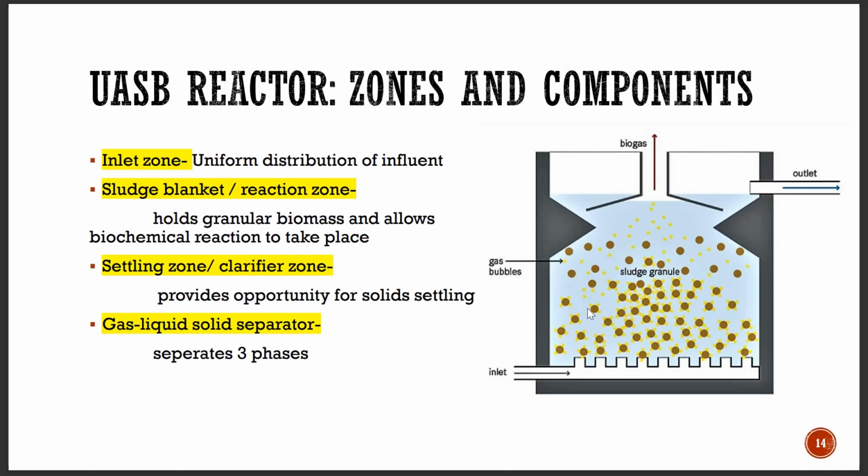So we do not require any kind of mechanical assistance or mechanical parts, it will happen on its own. When it reaches the top, these sloped walls will actually deflect the material that reaches the top. So these sloped walls will not allow the sludge to reach the top.